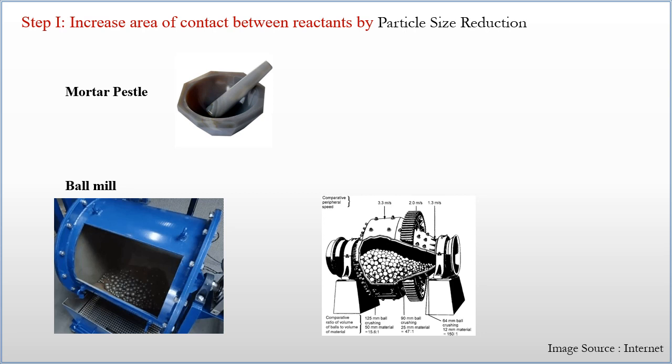But a problem is that if you carry out this ball milling process for a long duration of time, the material may heat up and the reaction may take place within this ball mill instrument also. So you have to be careful in choosing the time and RPM for breaking the particle size. If your intention is only to reduce the particle size, you have to be mindful of that.